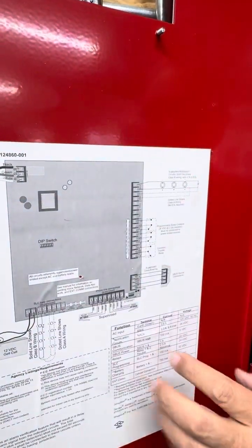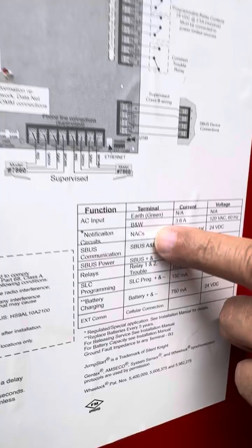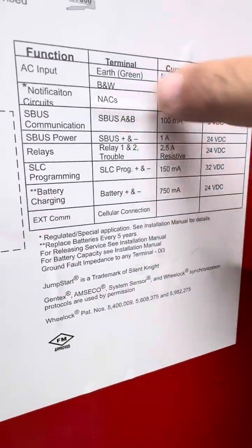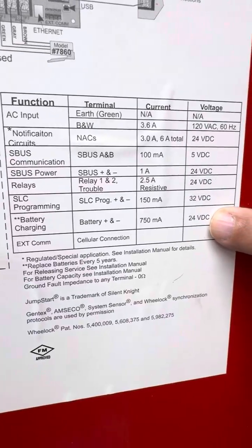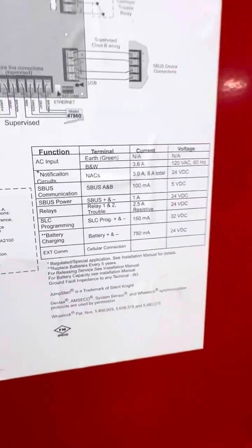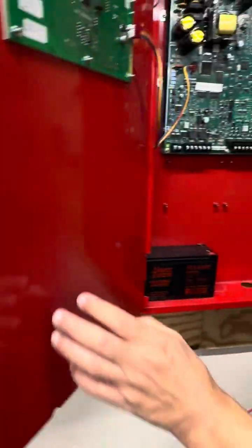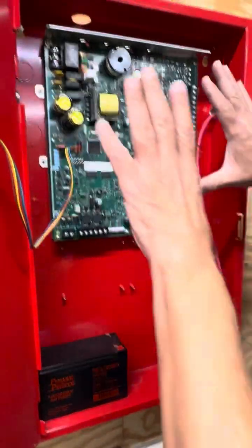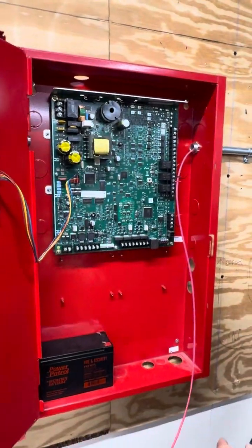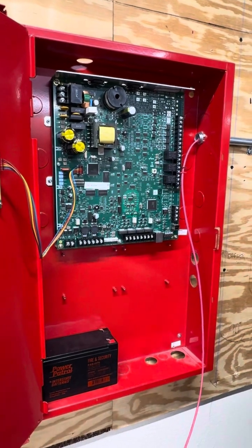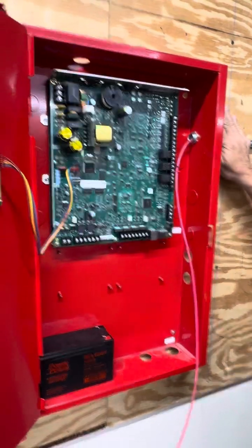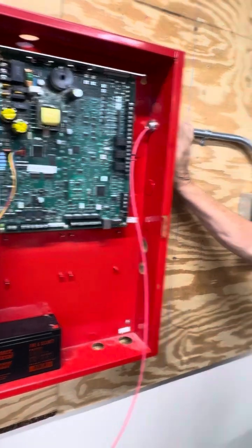this fire alarm control panel. And right here, we have the input, which is 120 volts, and all the devices here work with 24 volts DC. The precaution that we have to take when we work here is that before we touch anything, we have to touch any ground, any metal that is grounded in my system, to discharge my static electricity.